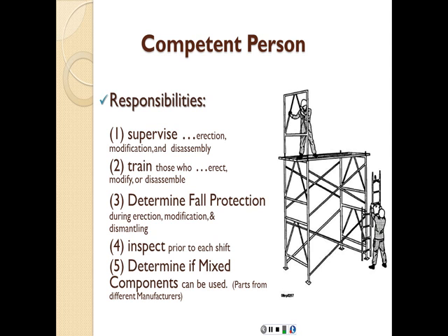or break. Inspect prior to each shift and determine if mixed components can be used, parts from different manufacturers. Sometimes you can use the scaffold that's completely manufactured by the same manufacturer, or you can use some generic components, connect them together, manufactured by different manufacturers. So we want to make sure that they can work together without causing a threat or a hazard to the people working on that scaffold.